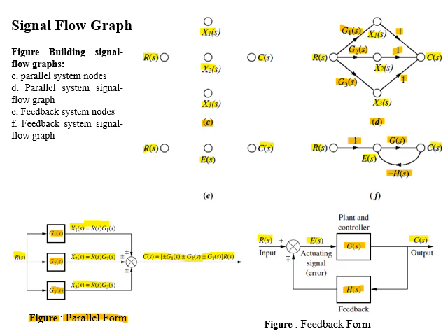In the feedback path, the output node and error node are connected with transfer function H(S), and here the output value of H(S) is being subtracted from input R(S), so the E(S) node will act as a summing junction, and the branch connecting C(S) and error will have a gain of minus H(S). Figure E represents nodes for the feedback form, where figure F represents the complete graph.